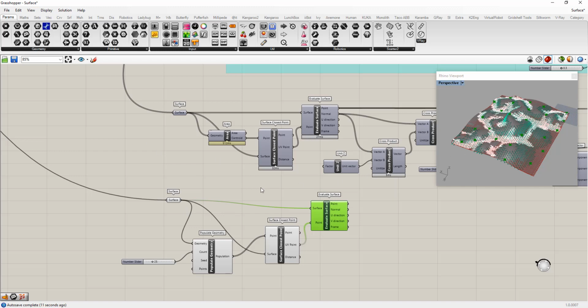And so from there, I need to get a line to use for my annotation. So let's make a SDL line, which is a line that has a start, a direction, and a length. I can take these points as the start. I can give it a normal direction, and then I'm gonna give it a length as well.